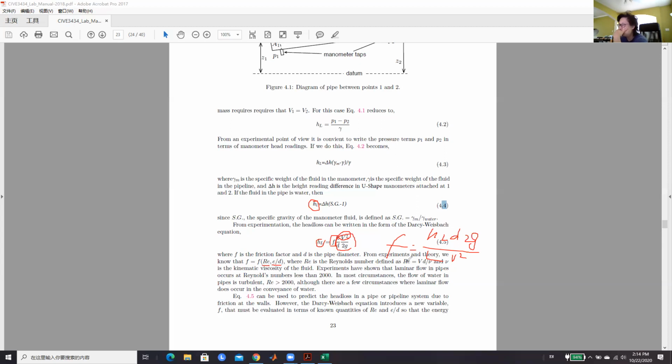Okay, and we also want to calculate the Reynolds number for each pipe, in different flow rate, because we are able to open the valve of the pipe. We adjust the opening, so the flow rate is different. Okay, we want to start from the very small flow rate and try to make the laminar flow in the pipe, and then we gradually open the valve a little bit by a little bit, so the flow rate is bigger and bigger.